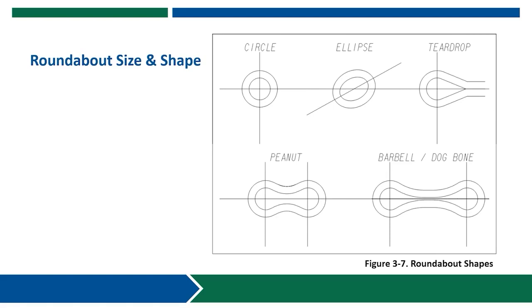They are used when two intersections are in close proximity, but there is a benefit to having a tangent connecting the two individual circles. And teardrop roundabouts do not allow for a continuous 360-degree travel around the circulatory roadway, and GDOT's preference is to use teardrops only when needed for operational reasons.